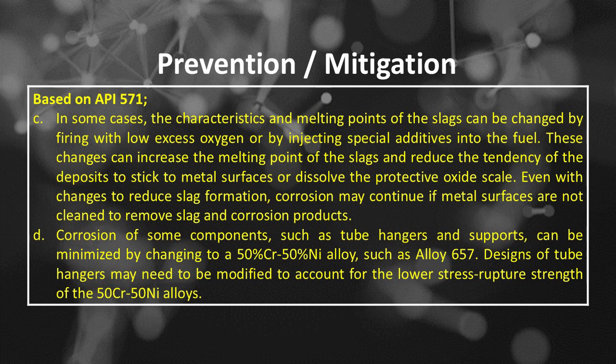Number C. In some cases, the characteristics and melting points of the slags can be changed by firing with low excess oxygen or by injecting special additives into the fuel. These changes can increase the melting point of the slags and reduce the tendency of the deposits to stick to metal surfaces or dissolve the protective oxide scale. Even with changes to reduce slag formation, corrosion may continue if metal surfaces are not cleaned to remove slag and corrosion products.